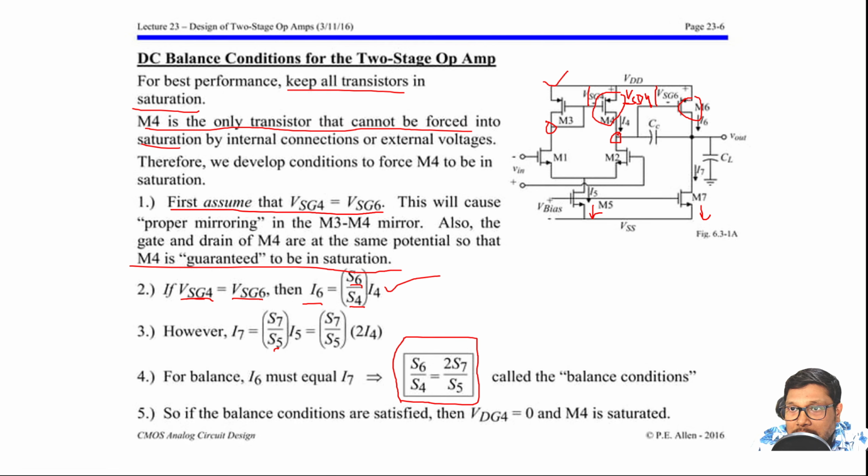So you can see, if you are increasing the current, suppose here I go for a multiplier. Suppose X current is going through this one, and you are using a multiplier of 10 here, so 10x current will go through this one. And if X is going through this one, 2x will go through this one.